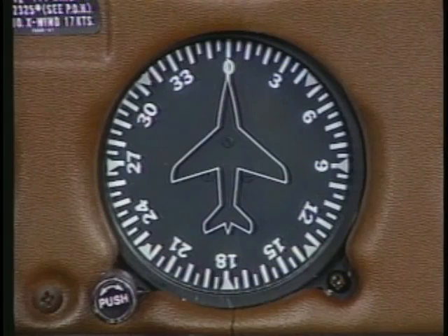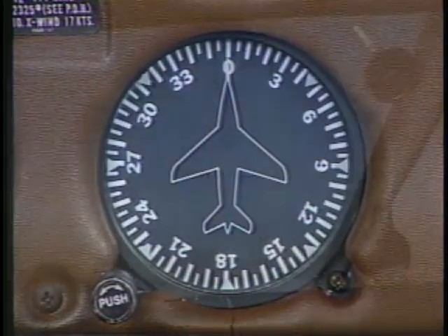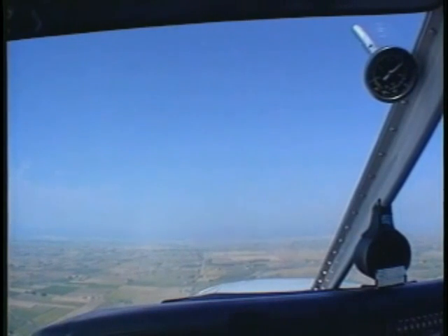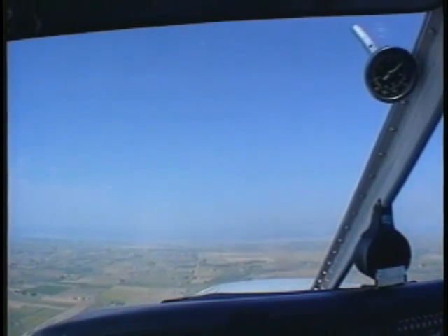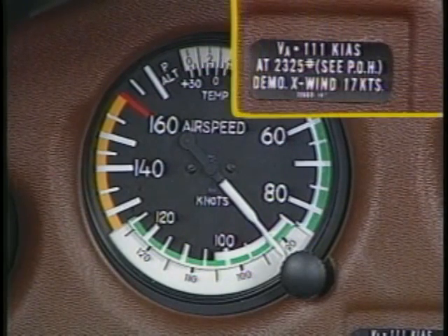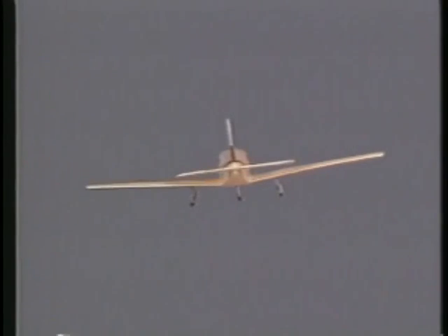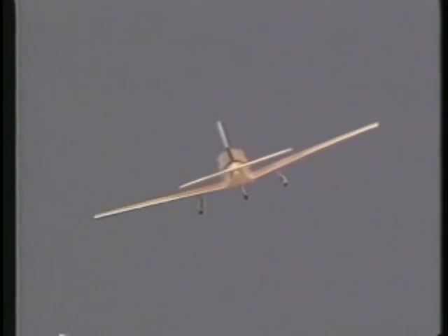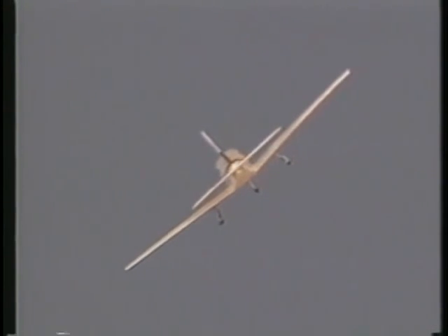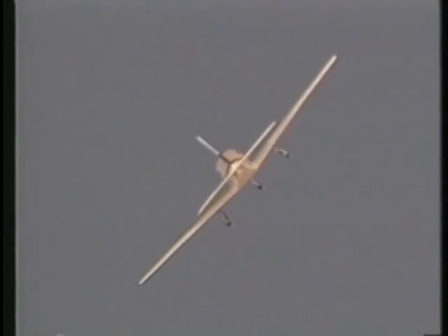Although any initial heading will do, you might find it helpful to start on one that is aligned with a road, section line, or other prominent landmark. The airspeed you select should not exceed the airplane's design maneuvering speed. This is very important because a steep turn substantially increases load factor. In a 50-degree constant altitude bank, the airplane is exposed to about 1.6 Gs.